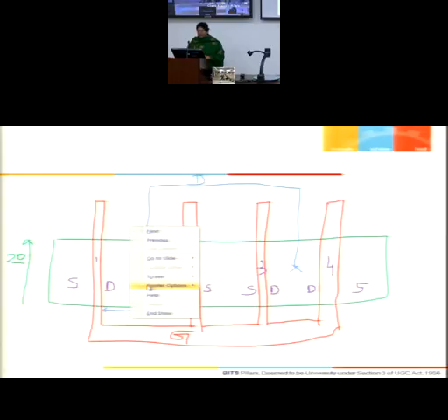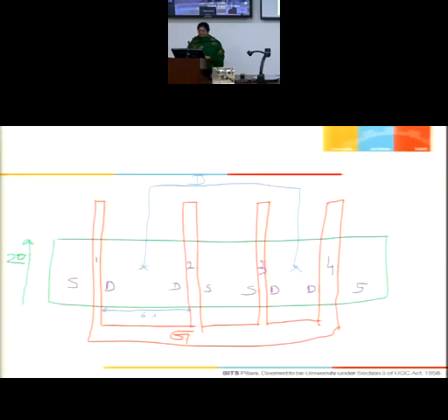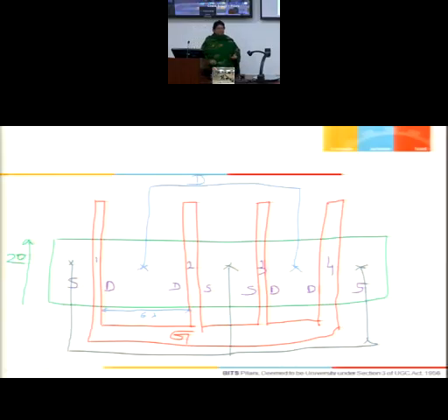And now I can choose a different blue color, so as to highlight the connection for the sources. So this is a source connection here, a source connection down here. Maybe I can use another metal. Now this metal, they are all connected and they can overlap poly, because in between is going to be silicon dioxide. So overlap does not mean a connection. Metal can overlap polysilicon. We all know that.